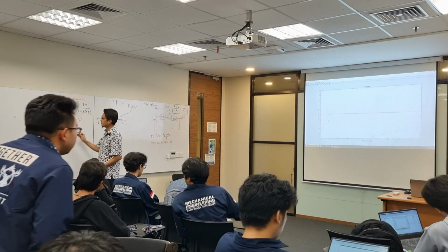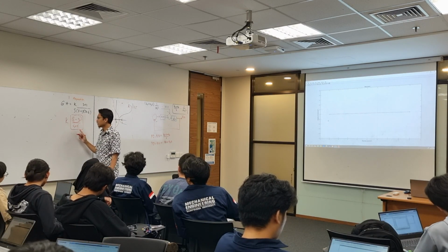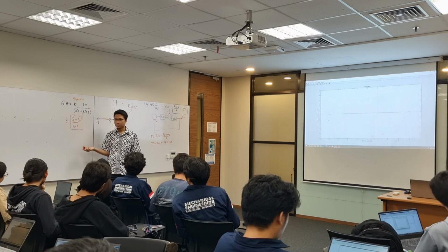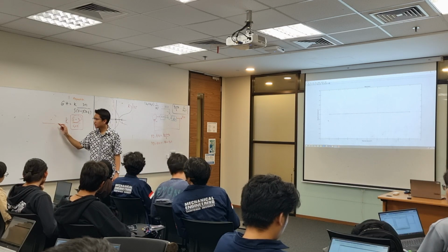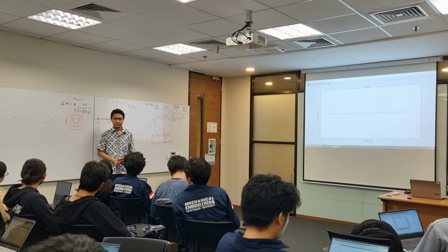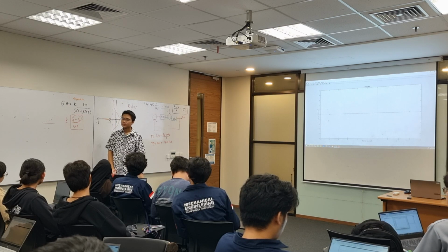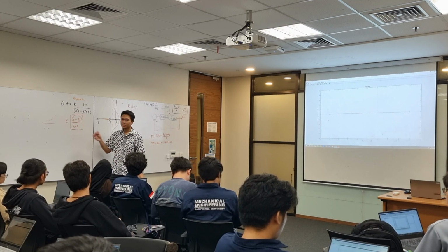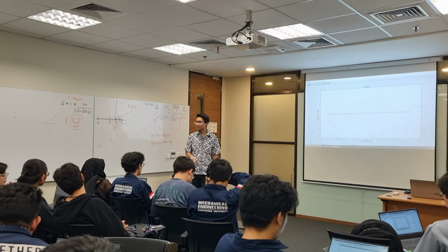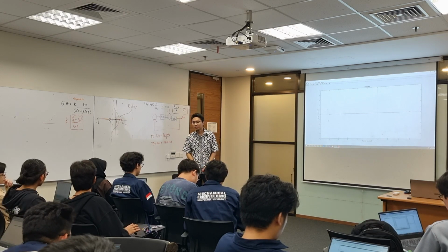Okay. For this system, what is your recommendation on the controller if you want to have a faster closed loop pole? What kind of controller will you have in there? You try. If it is PD, what happens? If it is PID, what happens? You can try. Check the open loop transfer function.